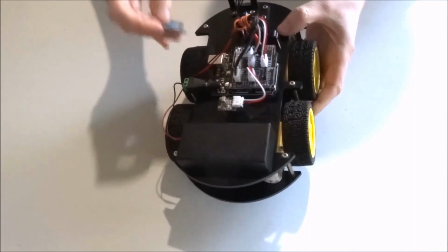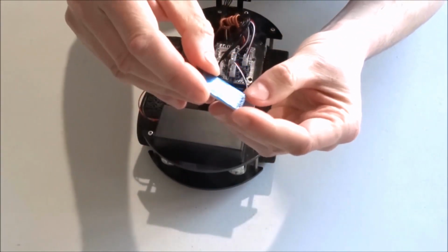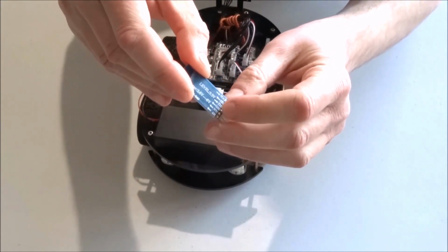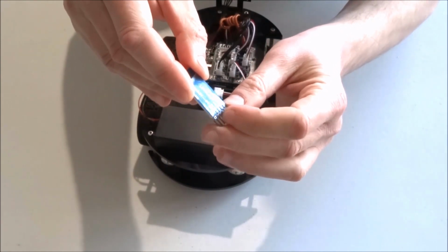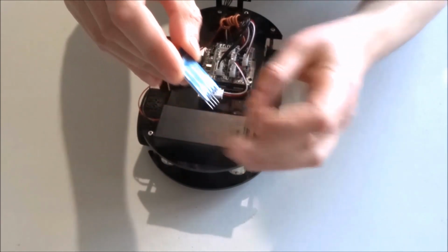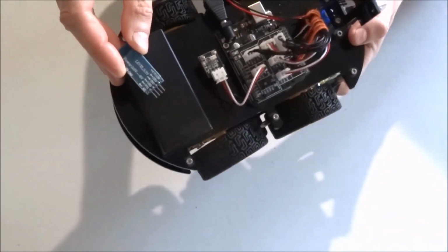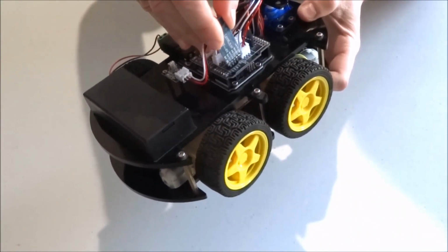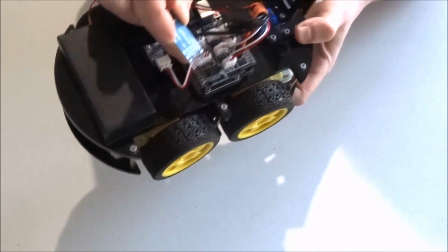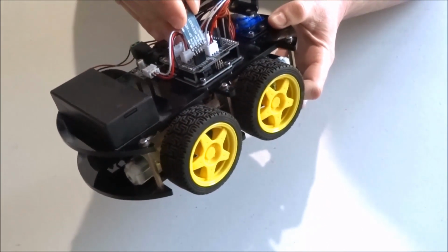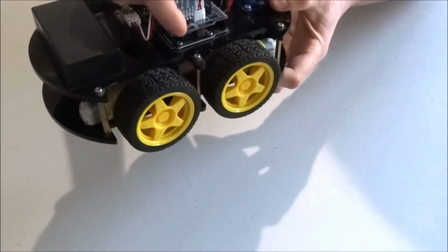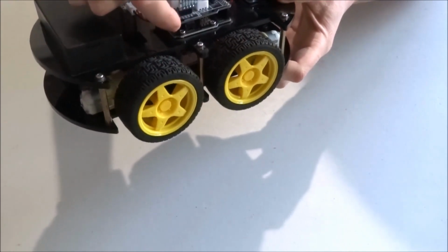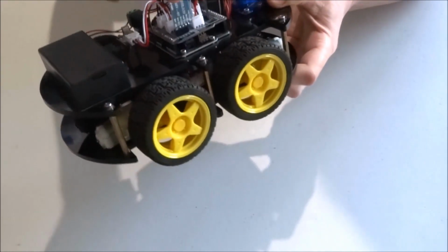and I can install the Bluetooth module. Please note that there are labels for the different pins on the module. This is VCC or positive power, ground, TX and RX. Their corresponding labels are right here on the Arduino shield. Make sure that the power and ground are matching exactly the labels on the shield, otherwise you may burn the module.